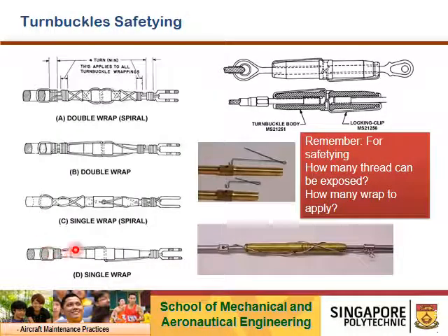This is the picture of a clip before installation. There are various sizes, depending on the turnbuckle barrel diameter. This is the clip. There is a part number given for the clip, available for you to order from the manufacturer. The clip itself is just inserted into the barrel and hooked onto the center of the hole. It will be easier for us to show you during the practical.